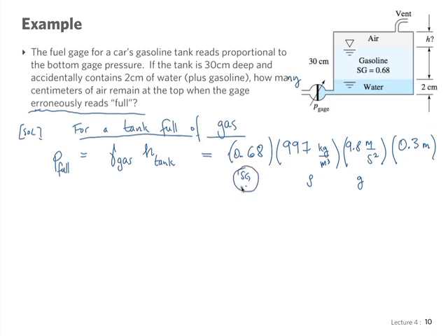Because we're multiplying by the specific gravity here. So the specific gravity is gamma of the gas divided by gamma of water. And so by multiplying by gamma of water, I get gamma of gas. So this is something important for you to learn how to use specific gravity in calculations like this. It's very useful because basically over time you kind of memorize the density of water for a certain condition which is obvious, or you use that table all the time, so you have your table for the density of water at 20 degrees or 25 degrees, and you're very quick with getting numbers out of it because you use it all the time.